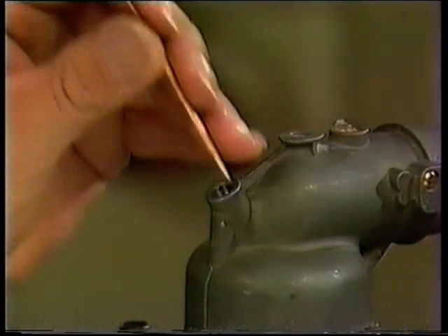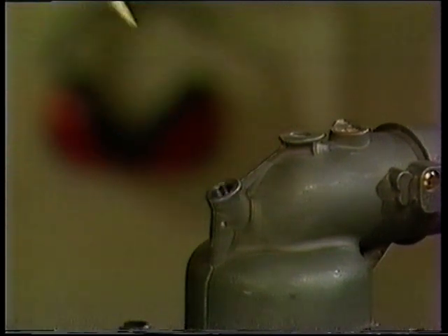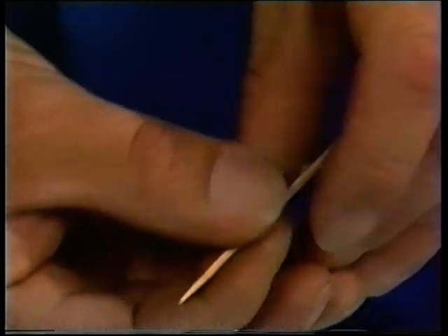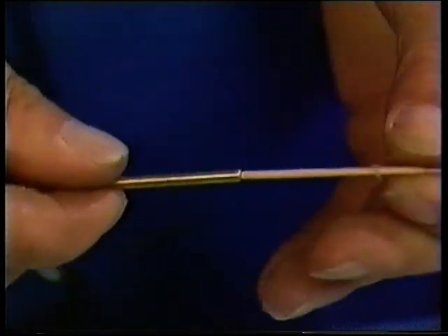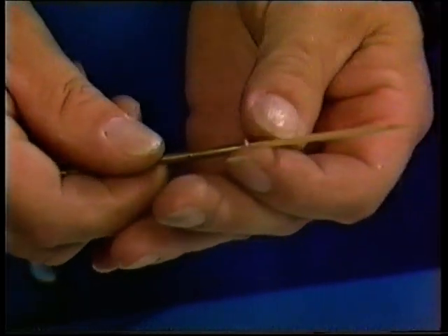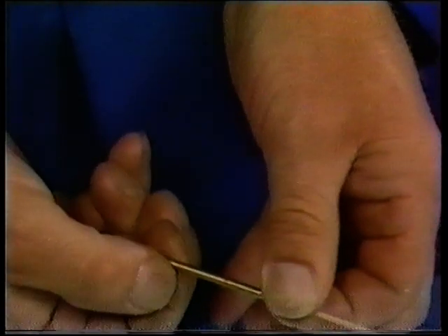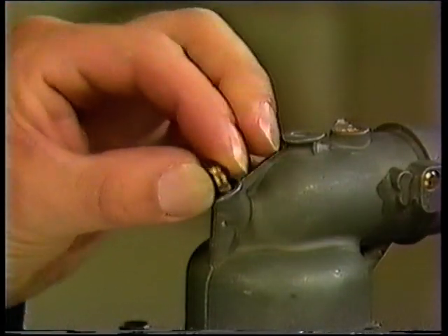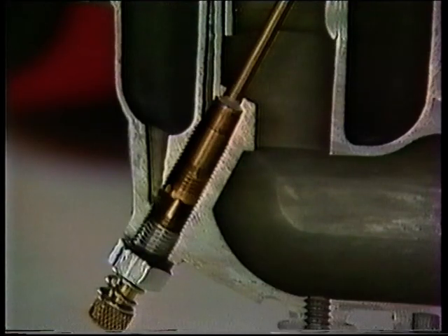Remove the old nozzle and completely clean the carburetor body. Now you'll install a new nozzle with one addition. Install the Teflon washer from a 391-413 carb repair kit over the tube, and seat it on the sealing surface of the new nozzle. The washer acts like a gasket, providing a better sealing surface for both the nozzle and the carburetor's body.